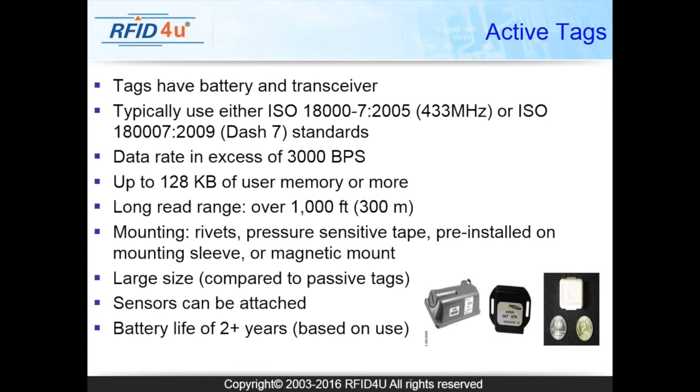They're larger than passive tags, once again, because you have the battery in there. You can also attach sensors to it, and the battery life is 2+ years, once again based upon use. If you're active and you set it to transmit every 10 seconds versus you tell it to transmit once a day, obviously you're going to impact the battery life.